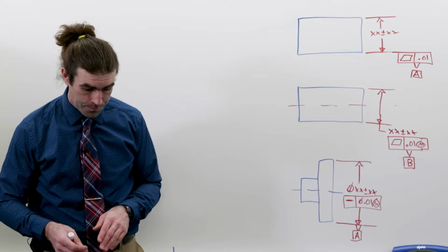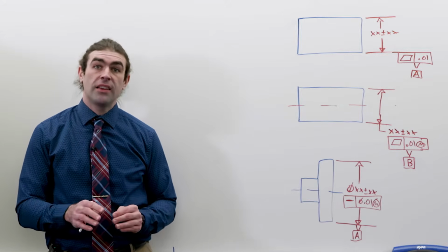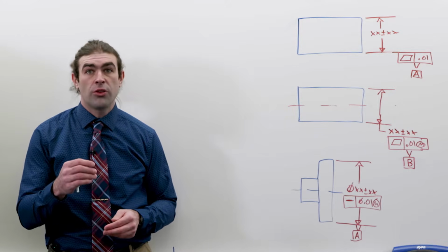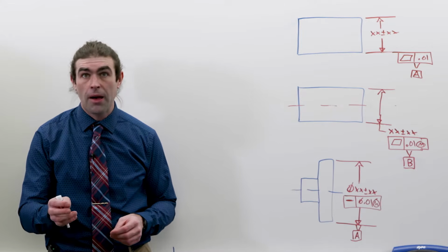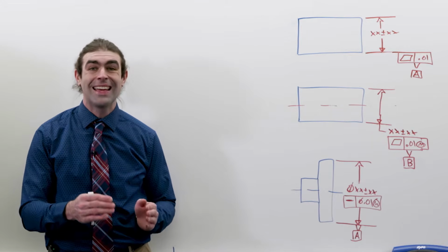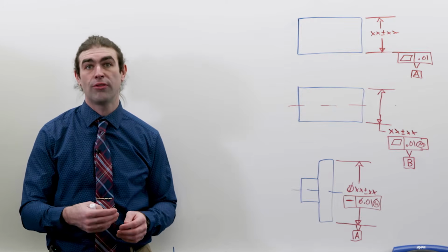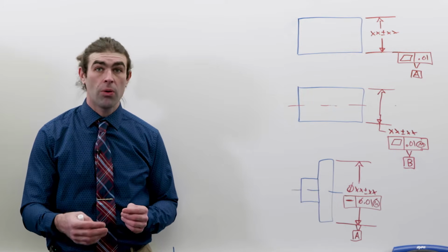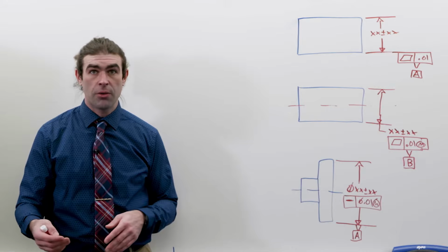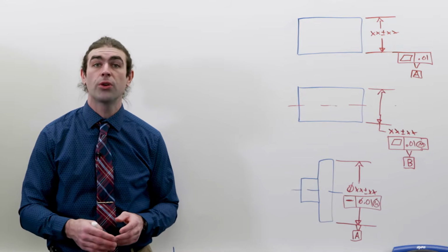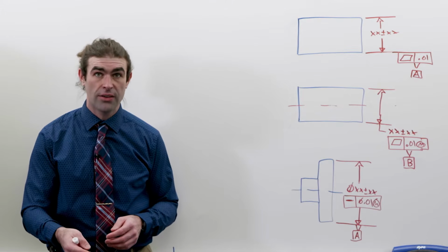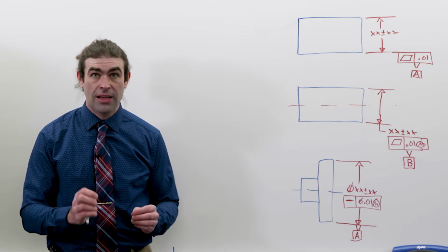Now I want to mention, in the 1994 standard, you are not allowed to put a datum feature symbol on a feature control frame unless it applied to a feature of size. So any drawing made to that standard, if you saw a datum feature symbol on a feature control frame, you could assume it was a feature of size. It's not that way anymore.